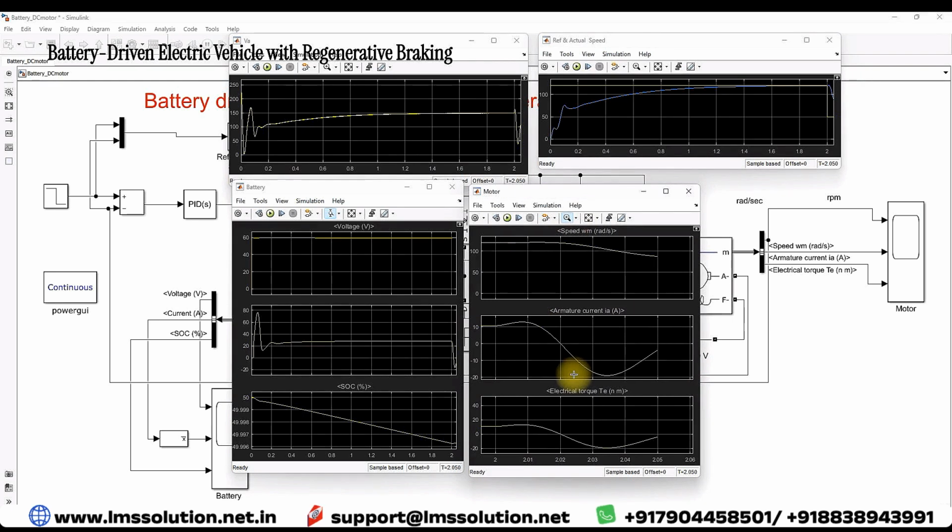Now you can see that the current of the DC machine or DC motor comes to minus 20 amps. When you apply the brake, the DC machine is going to act as a generator. That's why the current changes from 11 amps to minus 20 amps. And you can also see the electromagnetic torque of the machine changed from 11 Newton meter to minus 20 Newton meter. This is known as regeneration.